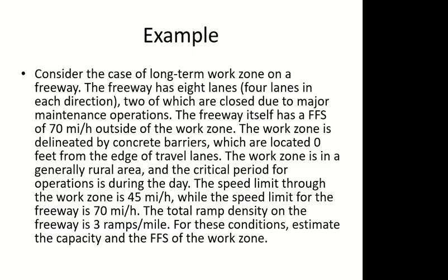We have shiny sunny weather 90% of the year. So should I take a factor for adjustment for weather in these conditions? The answer should be no. The weather condition adjustment factor should be taken in countries where this medium rain persists for a very long time, so most of the year you have rainy weather, like in the tropical region.